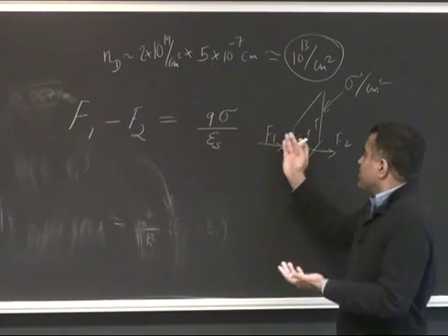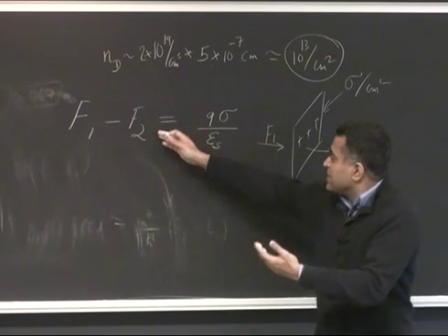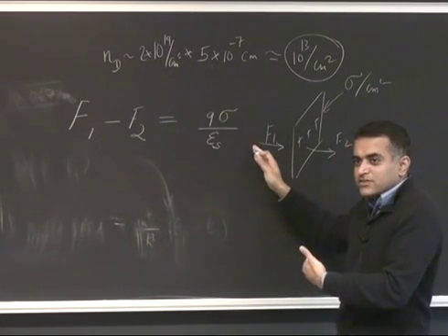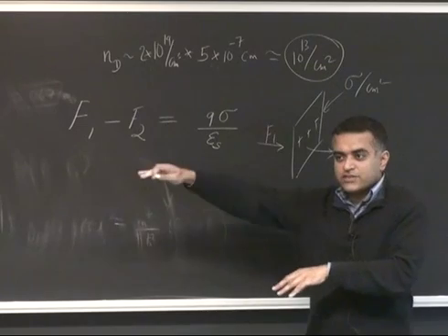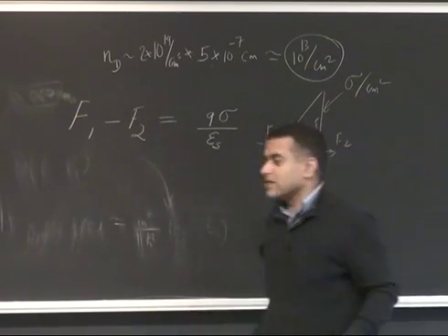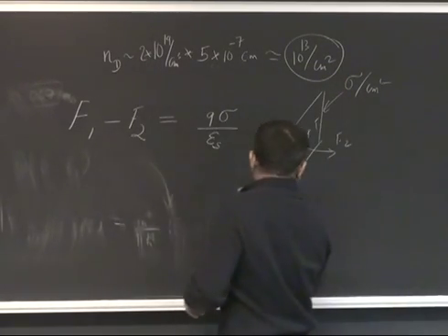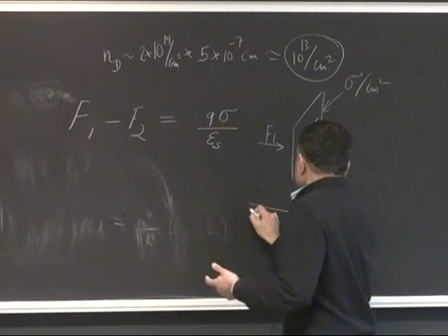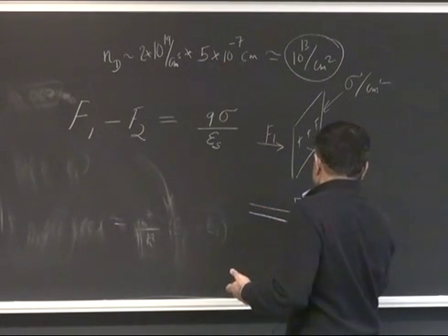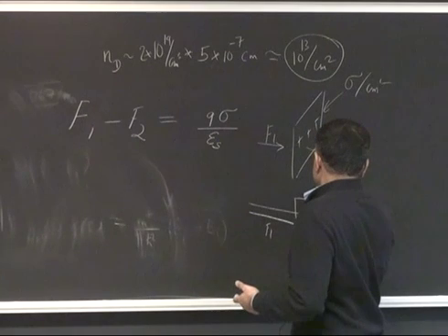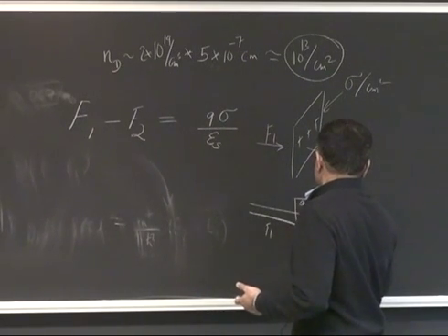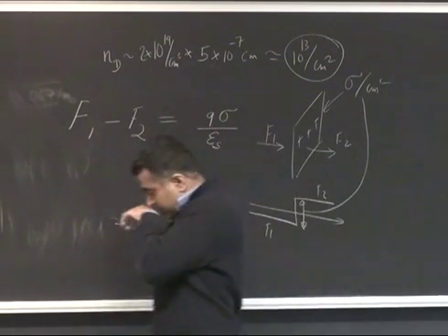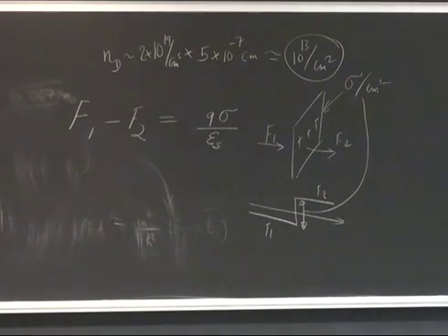Why? Because Gauss law, if you remember, the field is an integral of the charge, and there's a delta function. You integrate it, you get a step function. So you get a discrete step in the field. So the field profile goes, whatever it is on the left side, and then it will jump like that, F1 to F2, where this is the difference. And this is actually, in terms of just plain device design, one of the most useful and simple rules to remember.